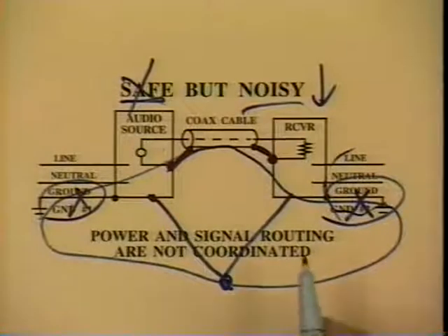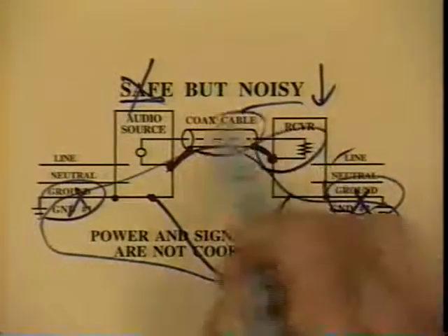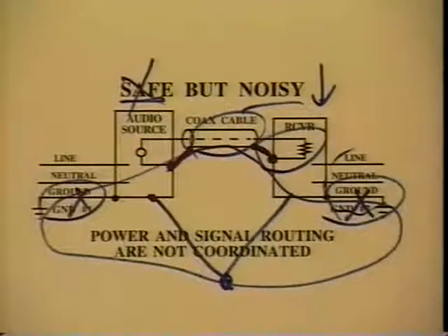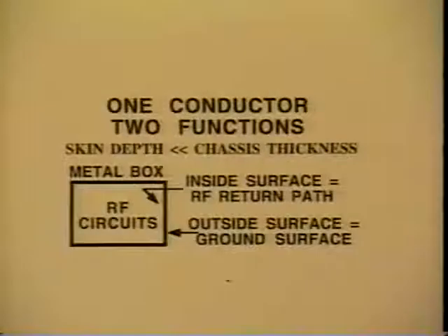Actually, what I'd really like to do is get rid of this single-ended receiver, get rid of this coaxial cable, use a twisted pair signal feeding over to a differential receiver, and then we don't have to worry so much about exactly where the chassis are grounded.